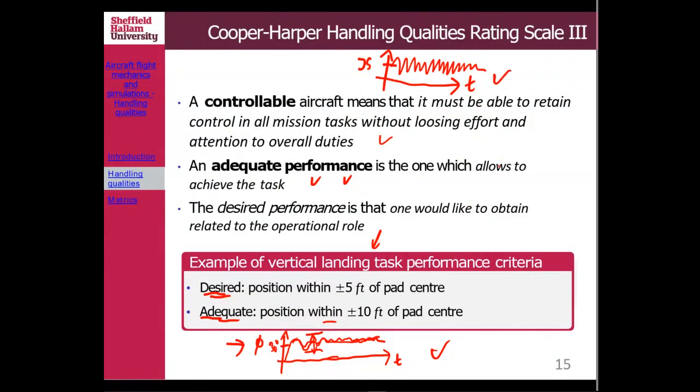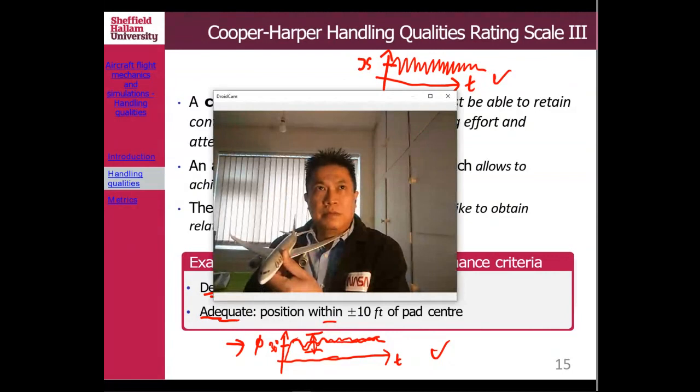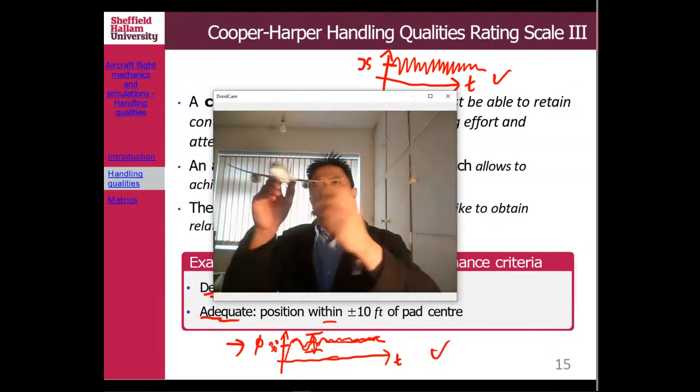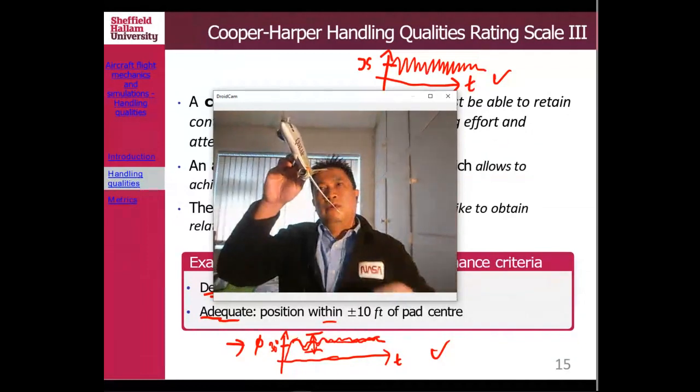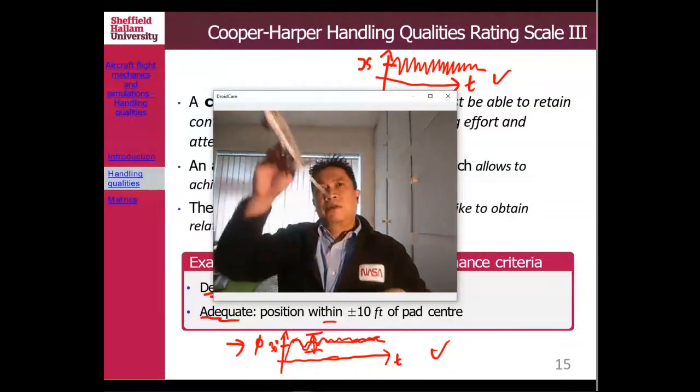You might also need to look into the reading of altitude when we talk about conducting the task of bank angle, for example. When you do the bank angle, a coordinated bank angle is important, so also look into whether your aircraft is slipping or skidding.